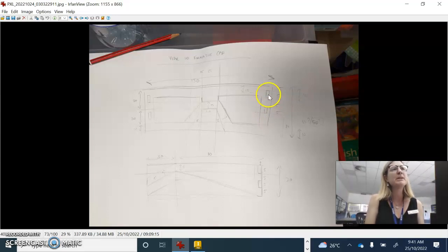And if there's 3mm material, so we know that that hole is 3mm, we want to leave probably around 3mm there on the side too. So this width here, I think we decided was going to be 10mm. So let's say that's going to be 3 and that's going to be 4 on the other side.